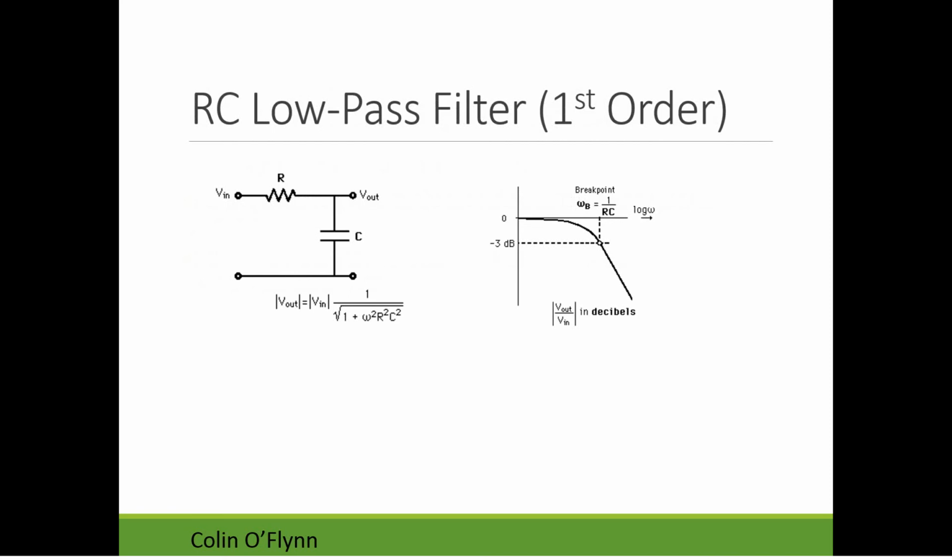All right, so the final thing to show you is actual filter design. This is the part that's really useful. The easiest type of filter is an RC, resistor capacitor, low pass filter. So we can do low pass or high pass or band pass with these RC filters. It just needs a resistor and capacitor, so very limited requirements.